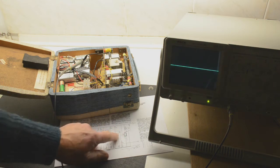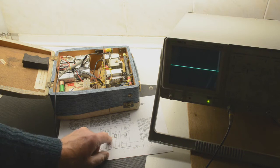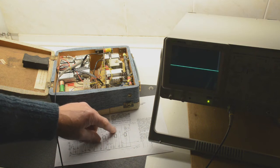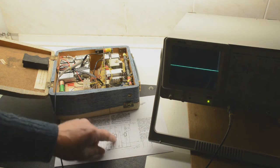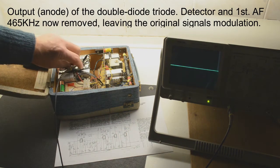Remember, in this we have 2 valves doing the audio. The first one here is the diode as well. So if we have a look at the output of this valve here, this is pin 5, which is the anode of the driver, the audio driver. So if I put that on, we'll have a look at the scope.